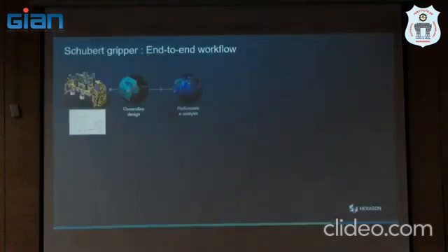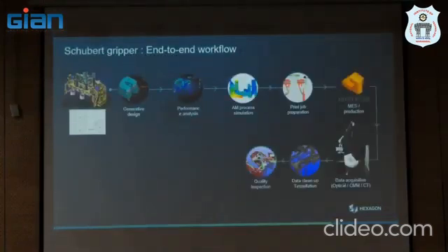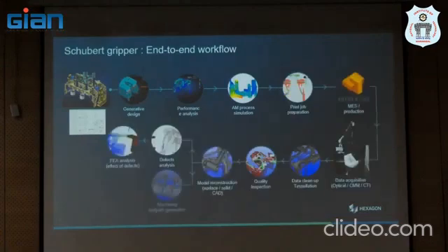So if you want to look at the end-to-end process, this is how it runs. This is a complete workflow of DFAM, material selection, and 3D printing. Start with your initial drawing, convert it into 3D, do the optimization, check the performance, then manufacturing feasibility, prepare for printing, print, measure, then quality inspection. If you require further correction, you can do it, then post-processing. So this is a complete cycle of implementing any 3D printing into an application.